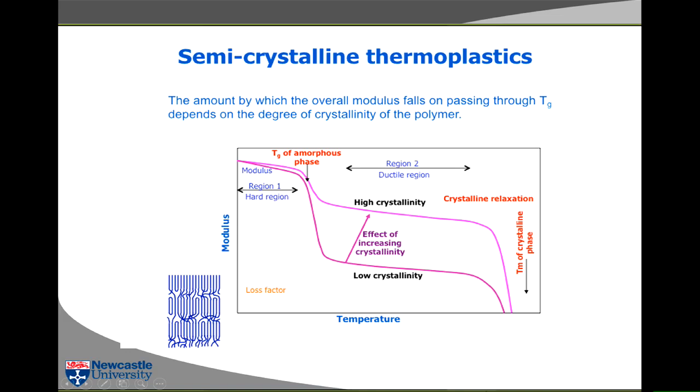But there's about a factor of 10 difference in Young's modulus between them. And you don't use low density polythene. Low density polythene is like the sort of polythene you use in packaging. It's not used in pipes. So all the pipe polyethylenes are high crystallinity, high density polyethylene. So that's what Young's modulus versus temperature for one of these materials looks like.